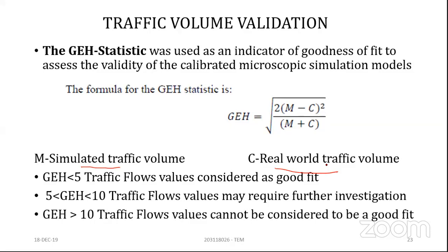It is mandatory to calibrate your data. So this kind of inference we can get from your GEH value, how it varies and how well it fits your simulated traffic volume with real-world traffic volume.